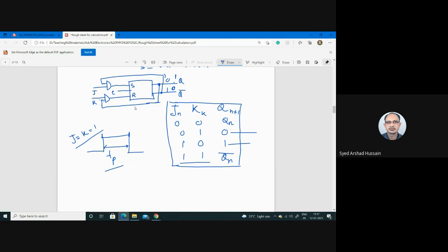Okay. So how can this be avoided? There is a simple way to avoid it, because once you are giving 1 here, it will go here, and it will read the earlier output. So the signal has to pass here, or for reading it has to come over here. If you can delay this passage, that means if you can lengthen the propagation delay up to this pulse width, then this toggling, that is the race between 0 and 1, may be avoided.